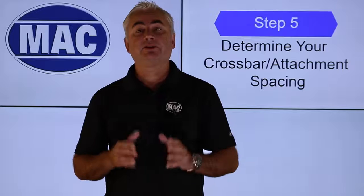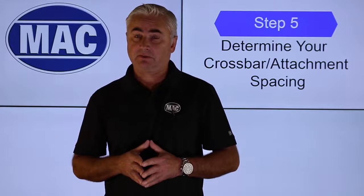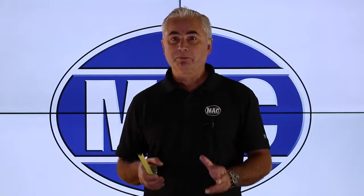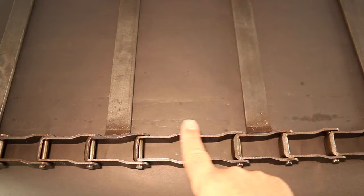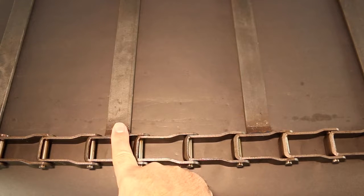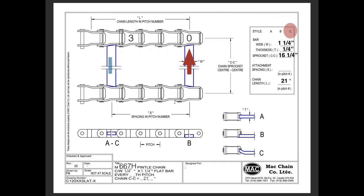Step number 5, determine the spacing of your crossbars. So to determine your spacing, locate a crossbar and that becomes 0. Now count up to your next crossbar. This is every 3rd pitch. In this example, this is every 3rd pitch.